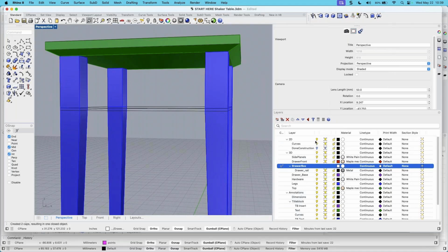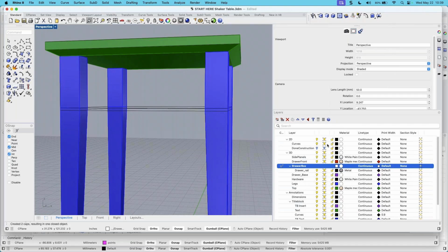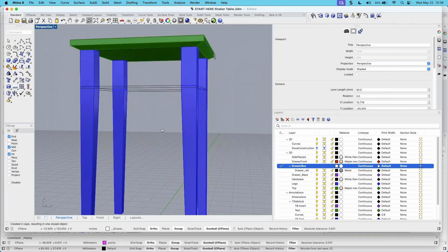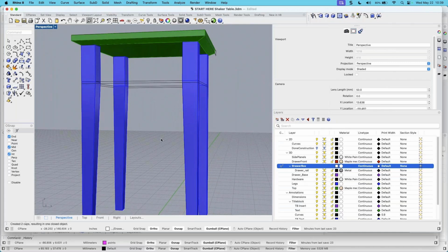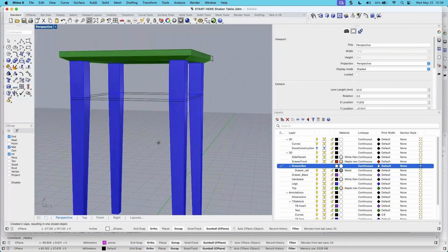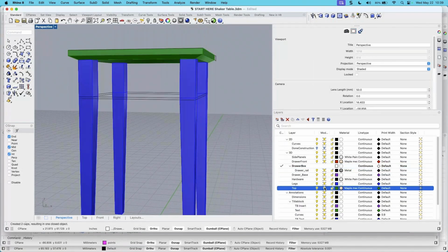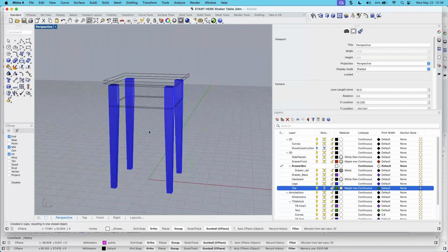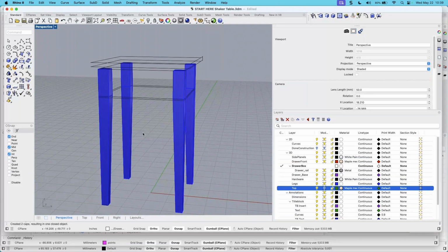So this is, I like to call this the global switch. It's like the power on your house. If you pull it, you're going to lose power everywhere. The second one is just for your room, and your room is your model space viewport. So if I turn off the top using this one, it's only off here. And if we did have those layouts set up, then it wouldn't modify the visibility in those layouts.